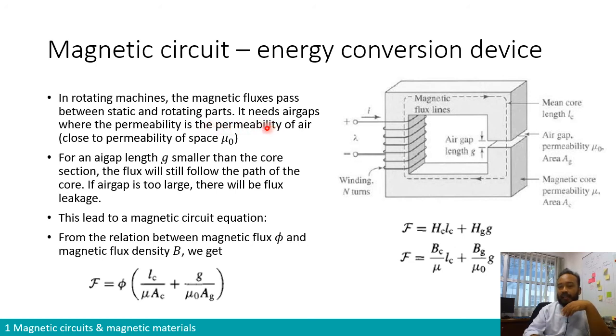what we call an air gap, because if you have two components, let's say a stator and a rotor in the middle, you cannot have friction between them in order to have continuous contact to allow the magnetic flux to circulate through it. So what you need to have between the stator that's not moving and the rotor that will be rotating is a certain air gap, right? It could be represented in this case as an air gap like this.